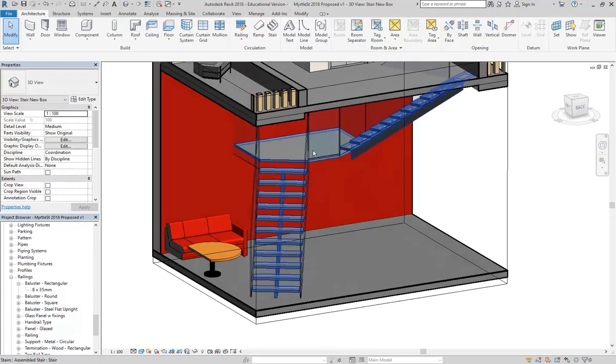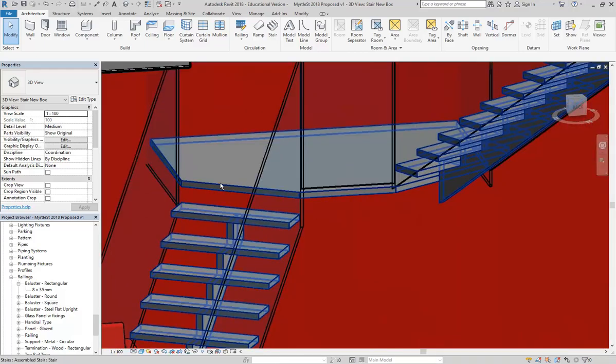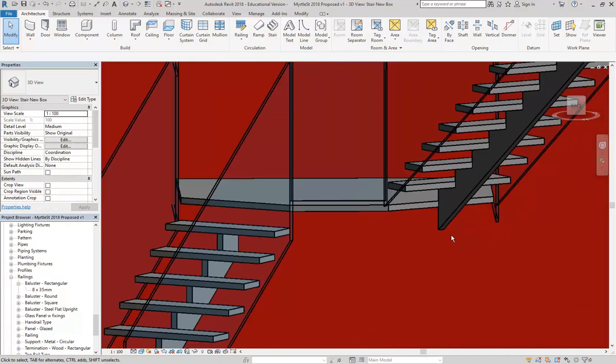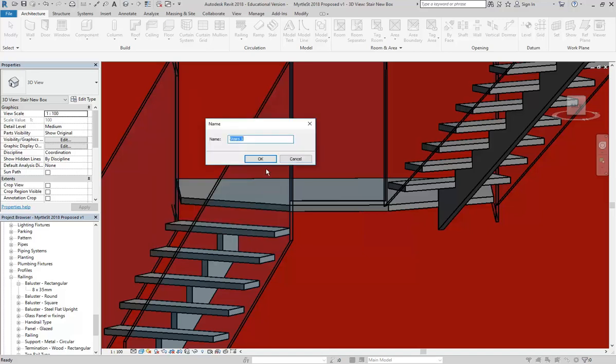So, okay, so then to put in a support for that landing, it actually would be pretty involved structurally, but to do a simple one for a concept type presentation, again, you could use model in place, so it's a good chance to show you a few tricks there. So I'm going to set the category to stairs, stair support, I'll call it.